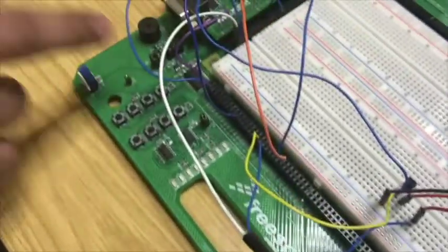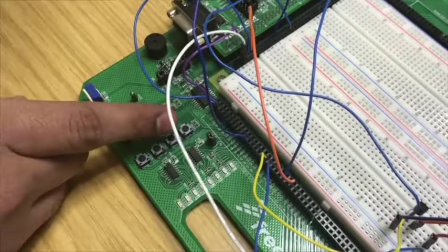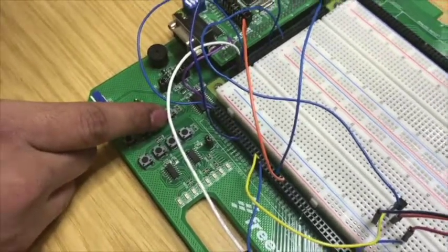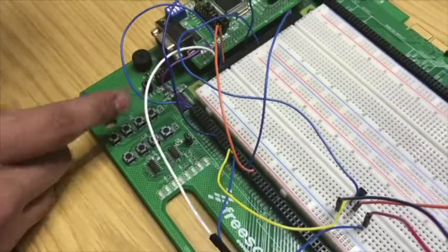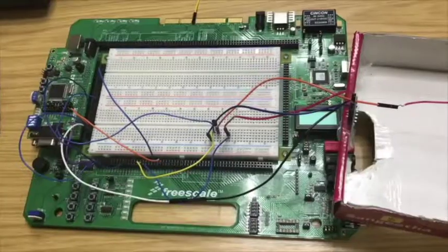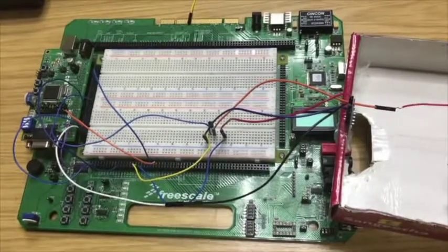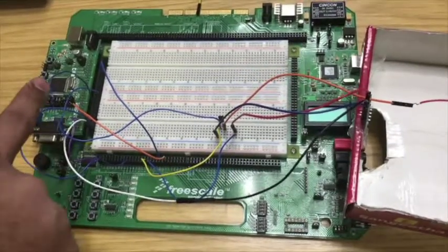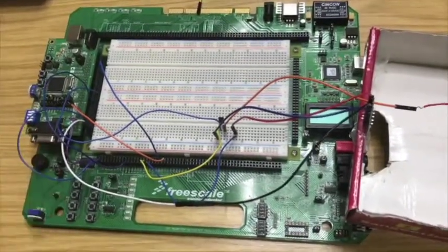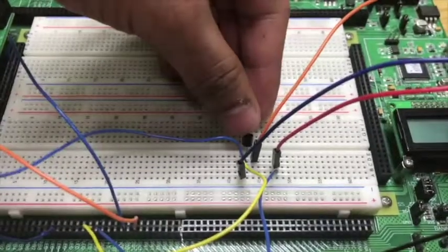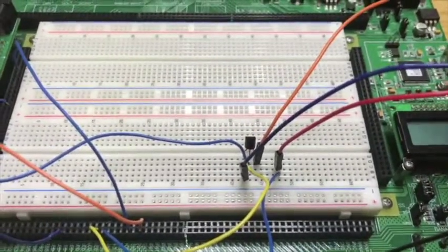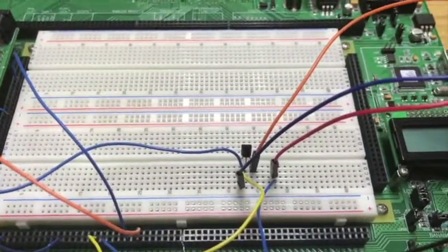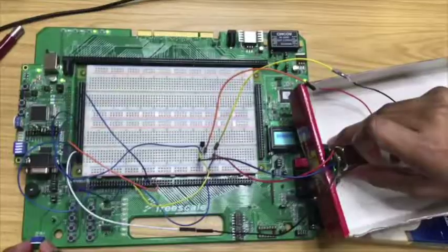The push buttons 1 and 2 are used to increase and decrease the speed of the DC motor by 5 RPS while the cruise control is in operation. When the cruise control is turned off, the control is returned back to the potentiometer. As the pulse width modulation signal cannot be directly used to drive the DC motor, an NPN transistor is used to act as a switch. The pulse width modulation signal is connected to the base of the transistor.